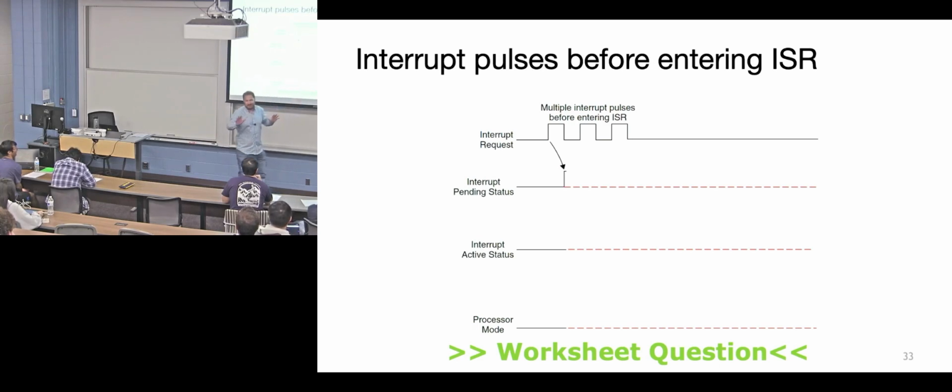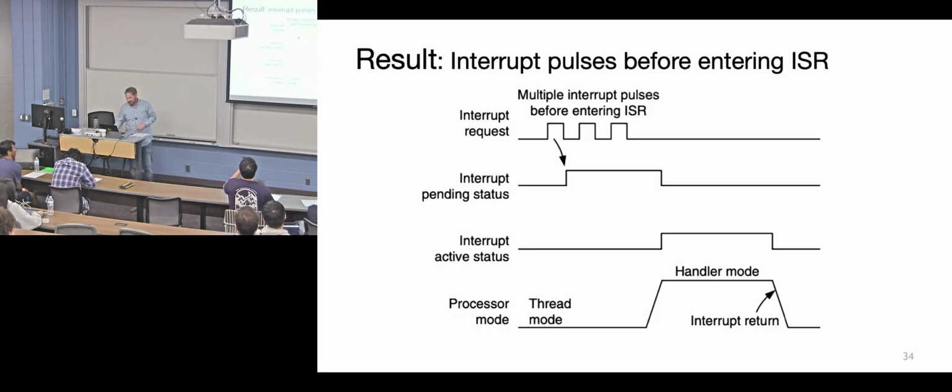So yeah, again, you guys didn't know that, but you're bringing up great ideas about some of the edge conditions. In this particular case, what ARM does, because it's all design choice, is say: this thing's going off and off and off, I'm only going to respond to it one time. When I get to it, then I'll respond. The fact that it went off 3 times, I'm just missing information, or I missed that event. I was not able to get to it fast enough.